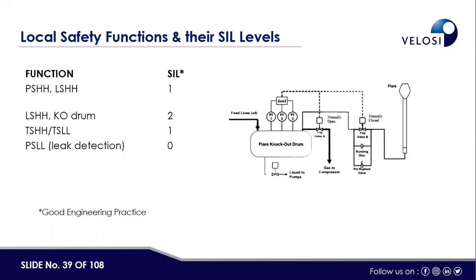EPC teams try to reduce the severity, and if they say there would be no fatality or no impact on the assets in case a hazard occurs, then the severity level would be low, and accordingly the SIL level would be low. Then if you are buying any hardware or instrumented function equipment, you may not be required to buy highly reliable equipment. It means the equipment could be bought from any supplier. It should be bought from a good reliable supplier with a proper track record.